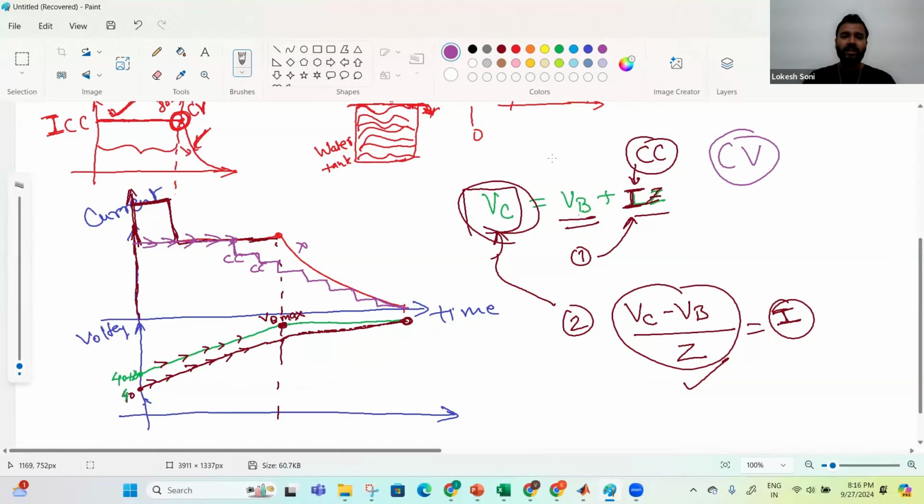That is one. Other is, once you charge your battery, after a certain time, temperature would also increase beyond certain reference threshold. So naturally, to address health, you would want to reduce the CC value so that at higher temperatures, the CC values are lesser. So it is one of the ways to optimize the charging in terms of the time and health of the battery. Okay, so again, MCC has its own reasons to do it too.